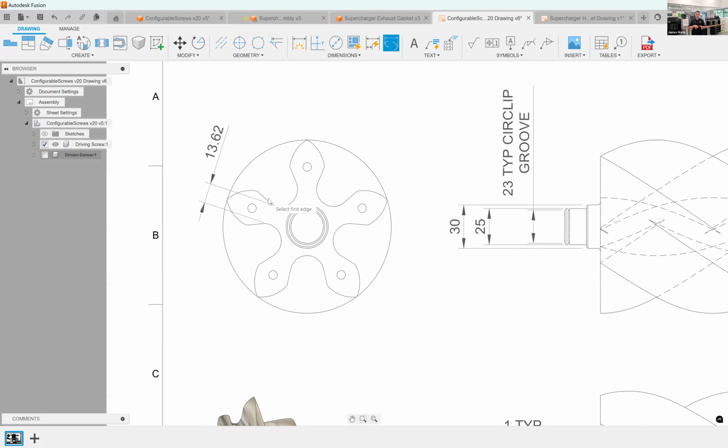That would have been almost impossible to do unless you created a sketch previously and dimensioned that sketch within the drawing workspace. It's called minimum and maximum because it also has some intelligent logic, and then it knows where you're clicking. So if I click on the outer edge of this circle here, and the outer edge of this one, you'll notice it does my outer to outer. If I do inner to inner, it's going to do the inner dimension. If I do inner to outer, as you'd expect, it's going to do the same in the middle.